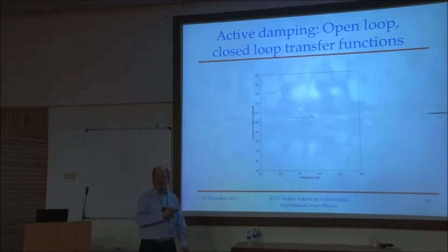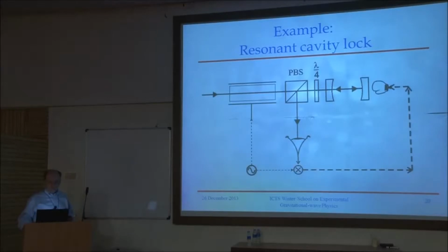Here in the narrow region of the peak, where G was much greater than 1, we've made a big difference. And by appropriate choice of signs and phases, we've just made 1 plus G a big thing, pulled this down. We now have a little bump instead of a big bump. But there's almost no change to the response elsewhere. So designing a servo is easy, right? Okay.